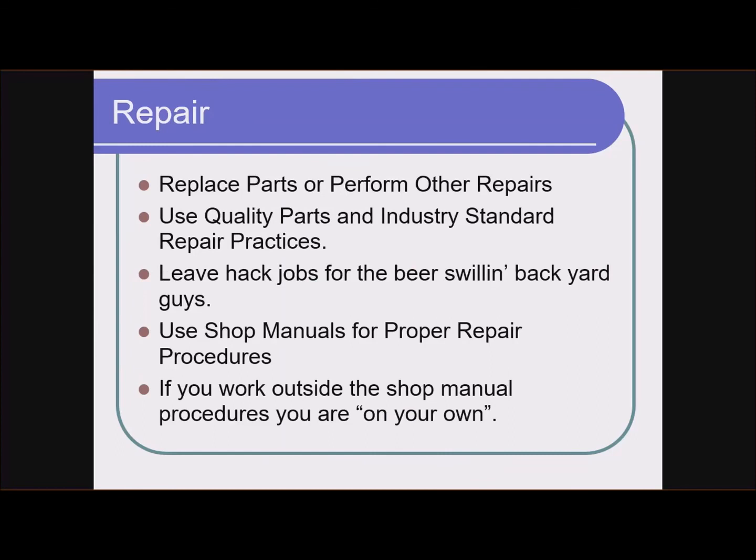So I began to doubt my diagnosis and think, well, maybe there's something else. But then again, engine's not reaching operating temperature. There really isn't another explanation except for a bad thermostat, one that's stuck open. So back up to Kmart and got another thermostat, put that in, filled the system, bled it out. Same thing, no heat.